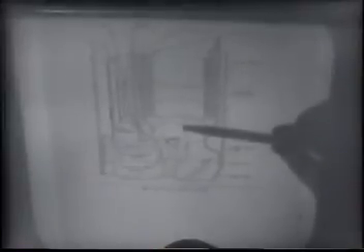Now, the contacts then continue to open, shown by these different positions here. And this tends to extinguish the arc by increasing the contact separation. As the contacts are separated, the heated arc column tends to rise through the different positions shown as 2, 3, 4, and 5.